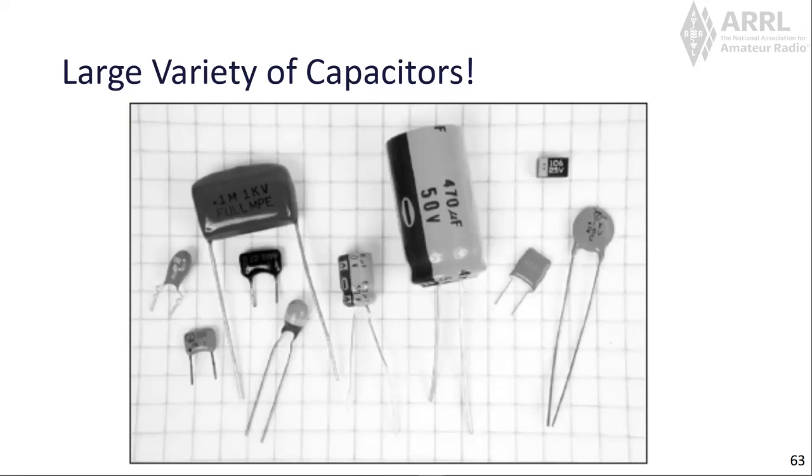So this one's 470 microfarads, and its maximum voltage rating is 50 volts. If you put something higher than that, it's going to short across, ruin the capacitor. Next.